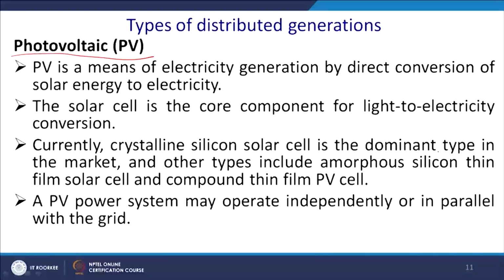You generally have three types of solar photovoltaic cell. Cheapest is the thin film, but efficiency is less. Thereafter comes polycrystalline, thereafter monocrystalline. We are going towards increasing efficiency and cost. So, monocrystalline is the costliest, having the highest efficiency. Thereafter, we have polycrystalline, it is the middleman in the road, medium efficiency and medium cost. Thin film, least efficiency and least cost.